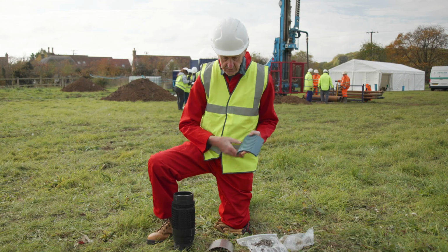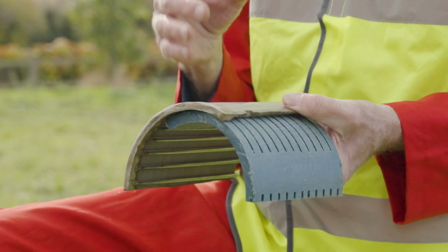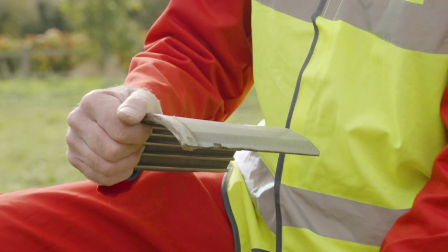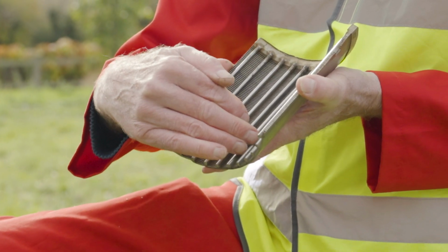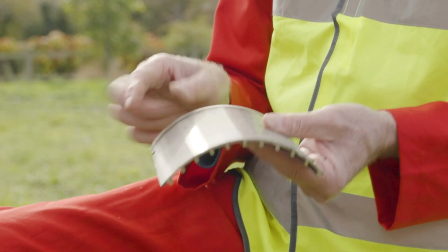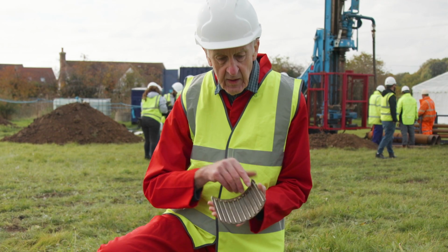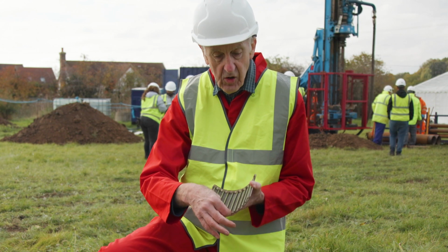PVC well screens of this type tend to have quite a small open area in terms of the percentage of the surface. An alternative is to use what's referred to as a stainless steel wire-wound screen, in which there are vertical stainless steel rods and a single wire which is wound around those rods in a spiral, and it's welded on at every point where it meets the rods.